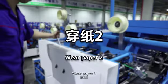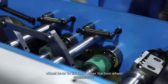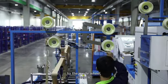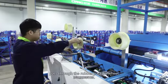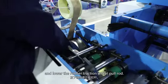Wear paper. Pull the rubber traction wheel lever to lift the rubber traction wheel. Pull the handle patch from the handle forming part to the guide wheel. Pull it through the positioning plate, pass through the rubber traction wheel, and lower the rubber traction wheel pull rope.